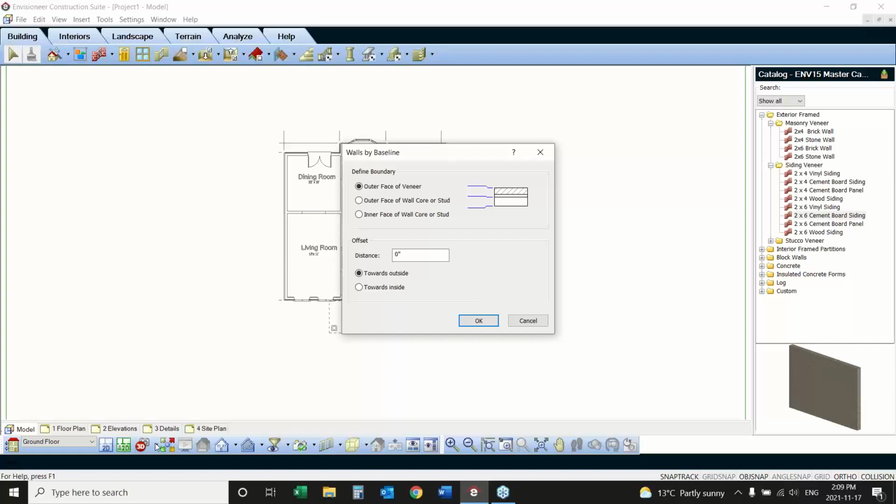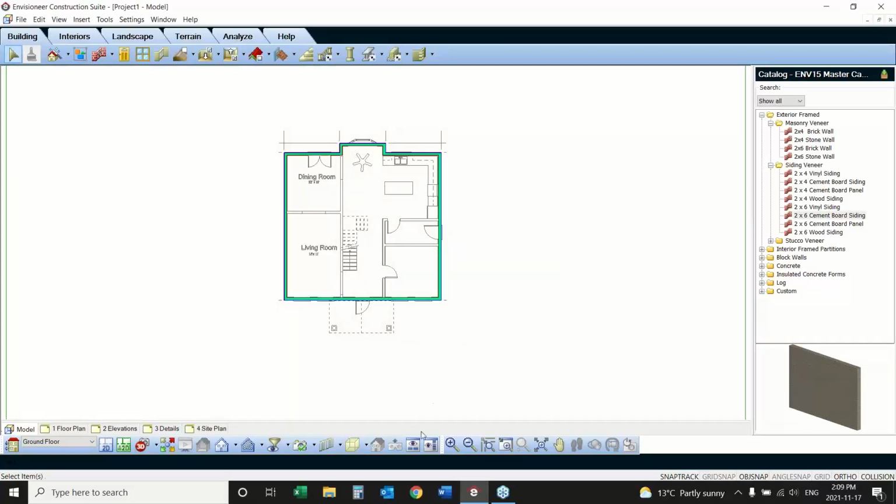It depends on the drawing that you're getting in. If they have drawn just the stud walls and not indicated the exterior finish, you trace around the studs and you tell it that you traced around the studs. And then you just click OK. From there, it highlights what we've already added into our estimate.